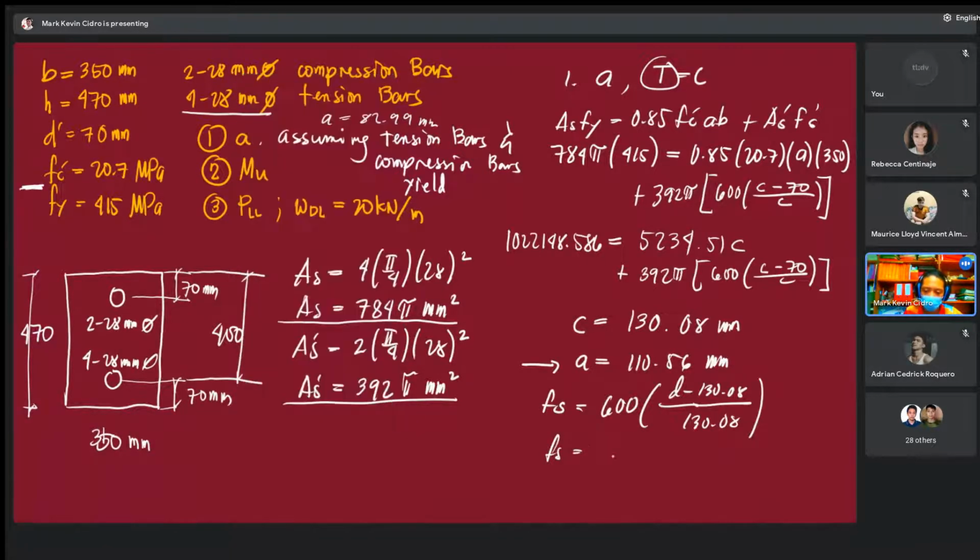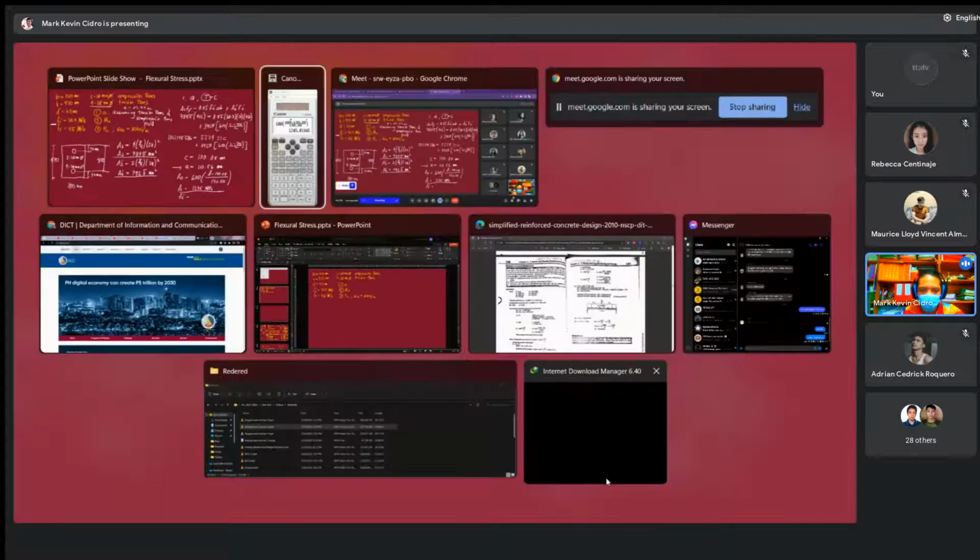The value written here is 1245, in megapascal. This is way beyond the value of Fy, right? So it really yielded. If you substituted that for Fy, the Fs formula gives too large a value compared to Fy, which is not right again, because your capacity for the steel is only limited to Fy. Okay, so for Fs prime, we can just go directly.